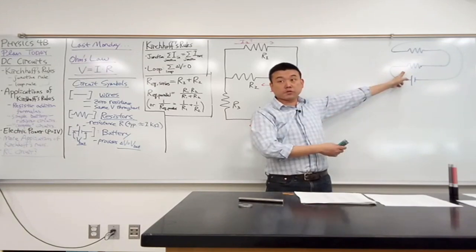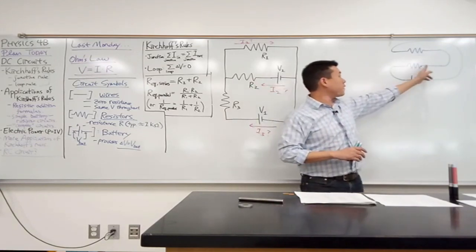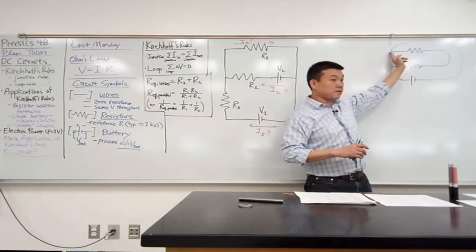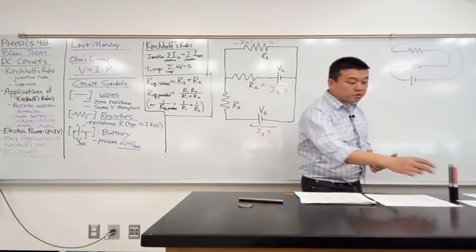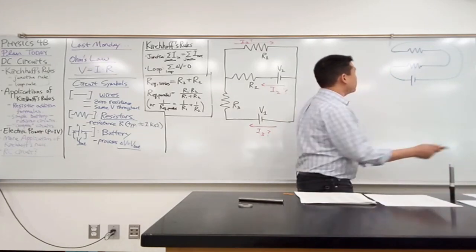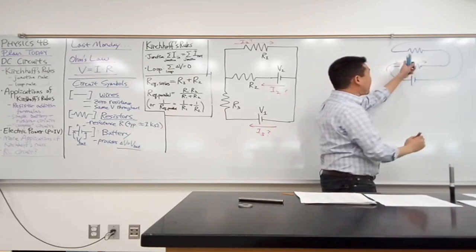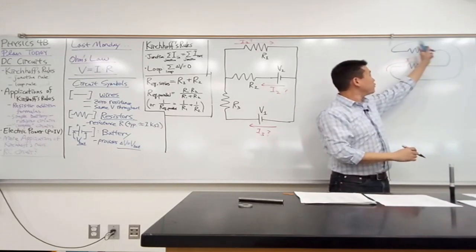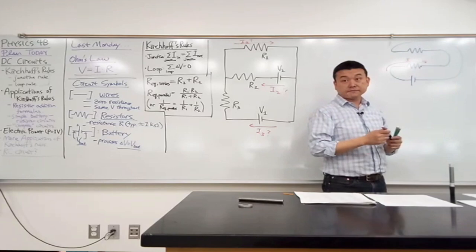One path for current to follow. You know, they are in series in the sense. One comes first, and then the other comes. So in fact, that's how we are always going to define series. For two circuit elements to be in series, that means when a current flows through one element, that same current must flow through the other element. Whenever that happens, we call that series.